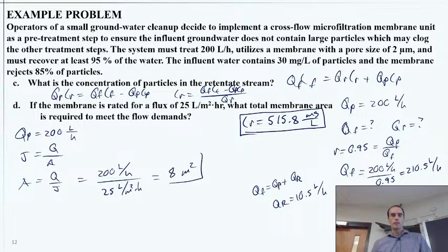All right. So we can see for part C, it's a little bit more involved. We need that overall balance of what's going in and out for the solutes. Means we have to find the flow rates, which means we have to get that water recovery rate, which is 0.95, equate that to what we're getting out compared to what's coming in, so we can know what's coming in.